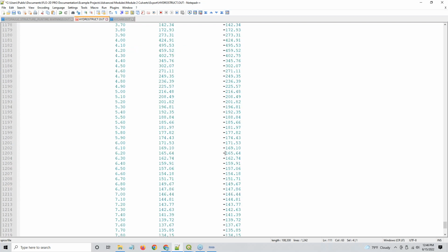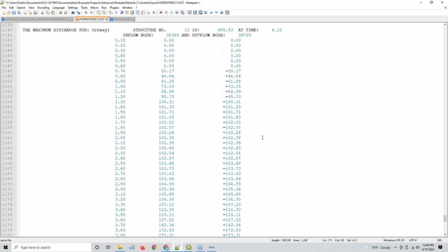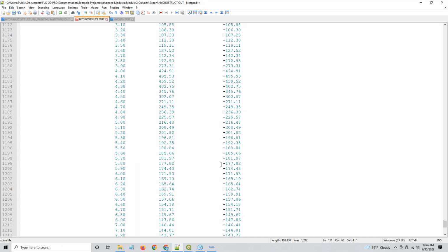I think I put 100 CFS into that, but of course there's also outside water coming into that channel as well, like rainfall and other structures filling it. So I think I gave it a steady state of 100 CFS, and then there's some other structures filling it. Although, I'm surprised to see almost 500 CFS in there.